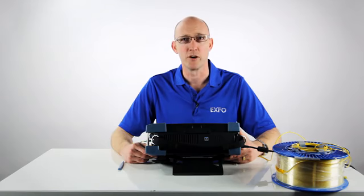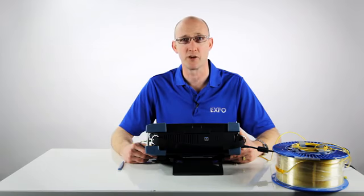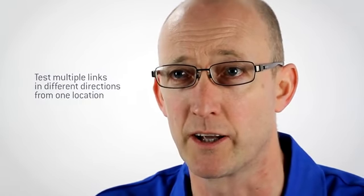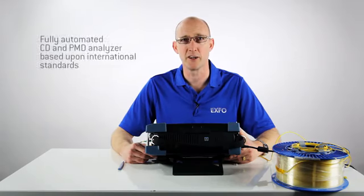The 5700 offers some unique advantages over the dual-ended systems on the market. Firstly, being single-ended, you only need one engineer to perform the test. So this reduces OPEX and saves time, as you don't need to wait for the other engineer to get to the other end of the link with the light source. Secondly, you can test multiple links heading in different directions from one location, again meaning fewer truck rolls and reduced OPEX.